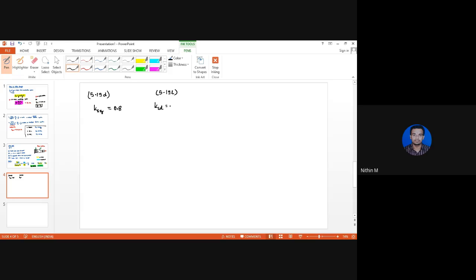If the ultimate strength of the material is less than 1520 MPa, it is 0.923. If it is greater than 1520 MPa, it will be 1. Here the ultimate strength of the component is given to be 580 MPa. Thereby the load factor KLD will be equal to 0.923.